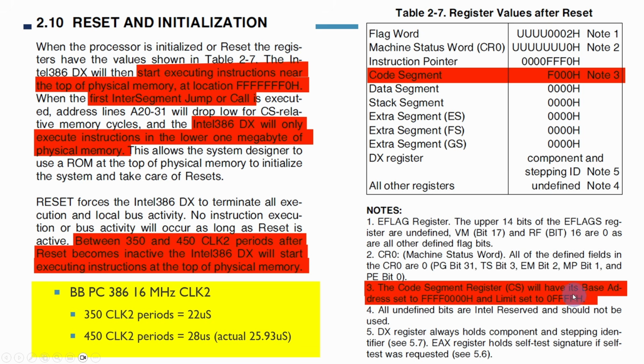On the original 8088, certain programs made use of that. So in the design we're going to be doing, we're going to be disabling the A20 line under some circumstances to ensure that compatibility. But in the basic mode that we're booting things up in at the moment, it's protecting ourselves from going back to 0 in memory.